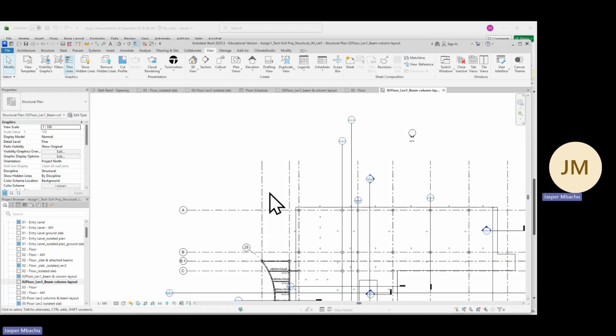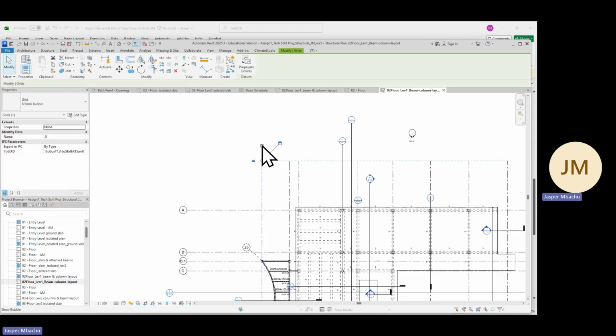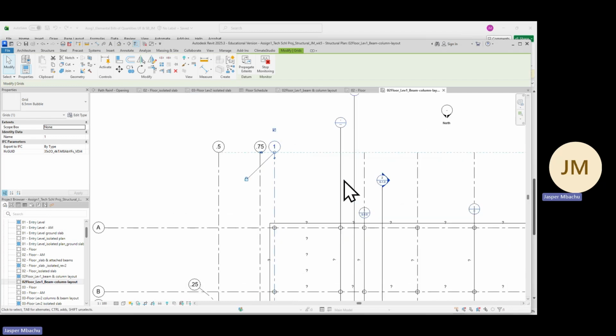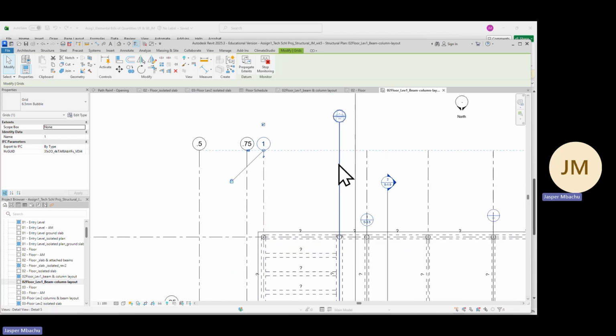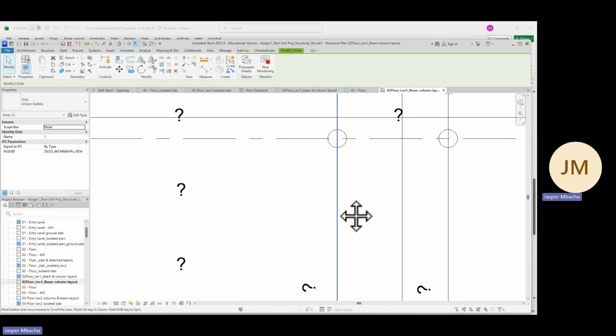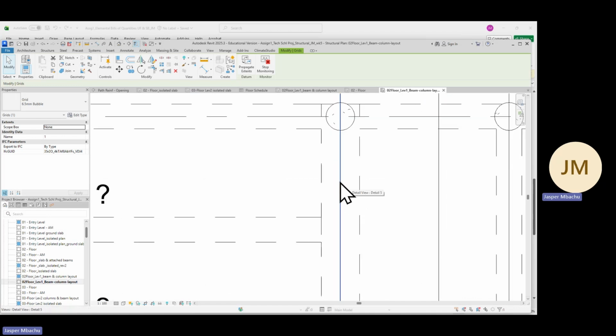And also everything that is in here, because of this structural formation on that grid line, let's first of all tick all these grid lines here. Click and tick, click and tick, click to display them on top. Wherever we see a grid line, there's a grid line here. Do you have a grid line as well as an annotation, a section box, a section line there? If so, come under the grid line, put your cursor there and use tab until you select it.